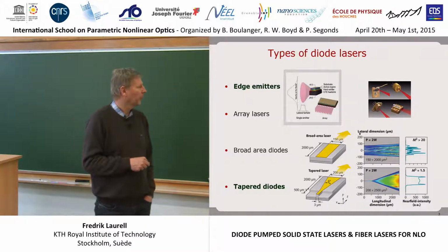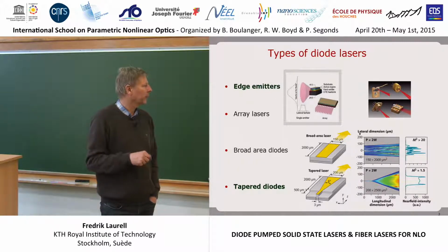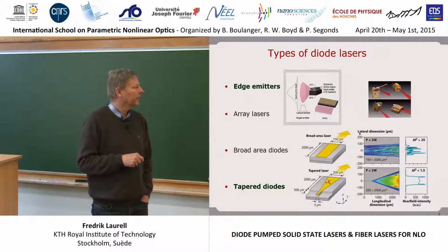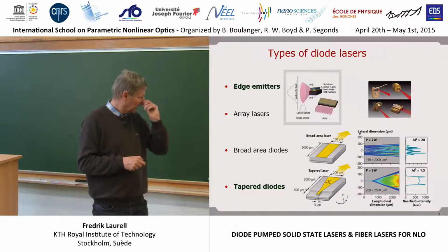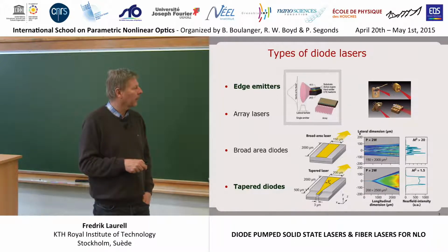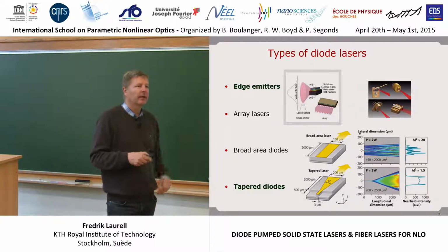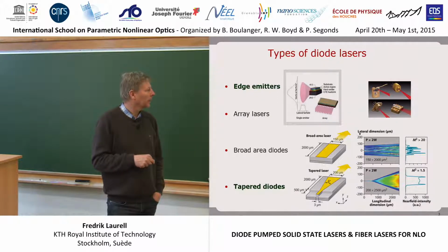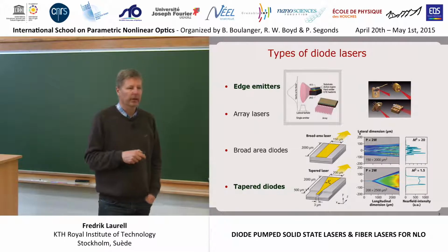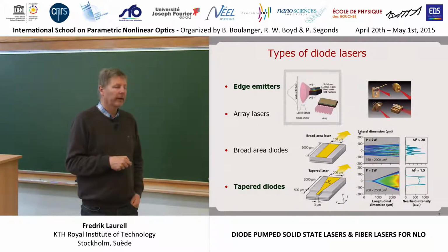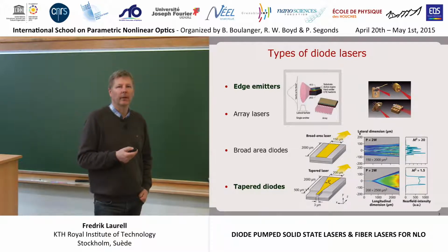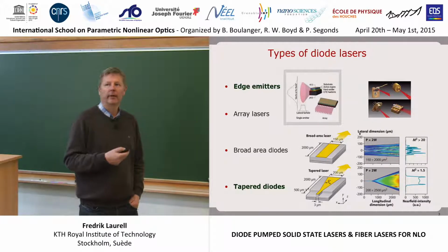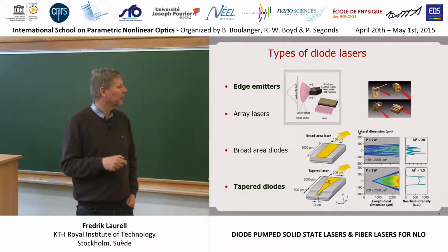But it's worth mentioning that this kind of laser was used by Matsushita for their laser TV. They put a lithium niobate waveguide behind it. And this laser is changing the mode pattern all the time. It means that the second harmonic is also changing all the time on the output, not only spatially, but also spectrally. This means that they lose all the coherence, and coherence is one of the big problems in laser projectors. So you have to kill coherence. This is something they got for free, and that's what they have in their laser TV, if you take it apart.